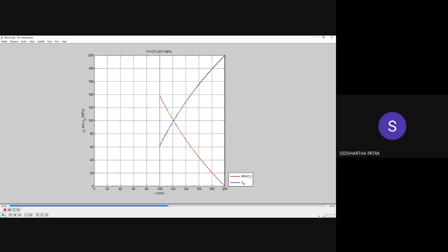Okay, so what it is showing is the different phases of unloading, and how much the stress changes. Once I have completely unloaded, there is no internal pressure, right? And then I would expect sigma r to go back to 0. So sigma r should be 0 at the minimum value, that is r equal a, and it should also be 0 because of the boundary condition at r equal b. Just check that.